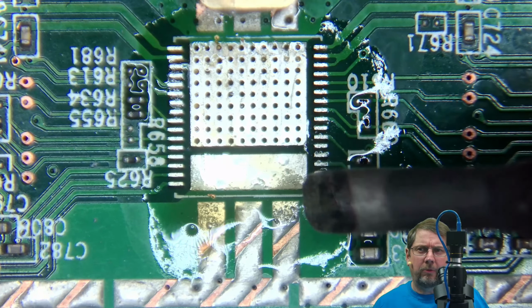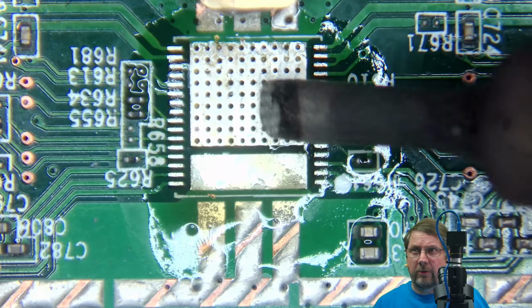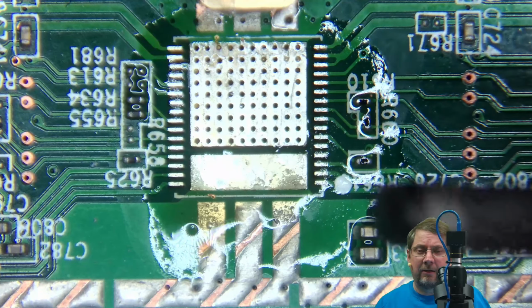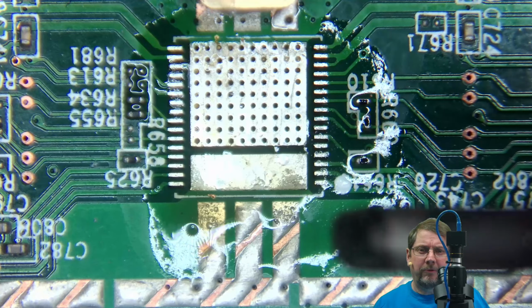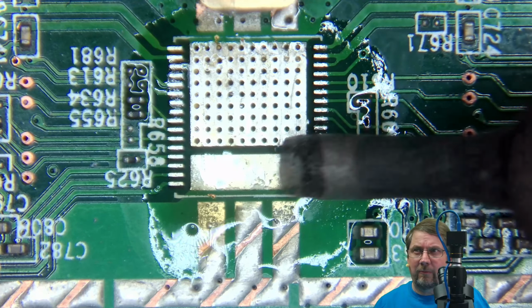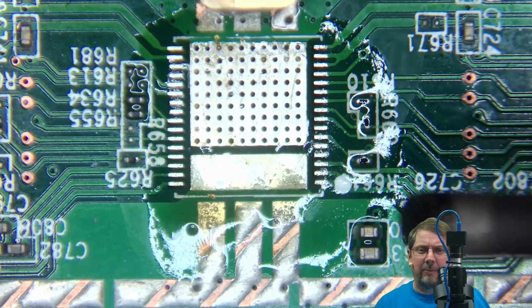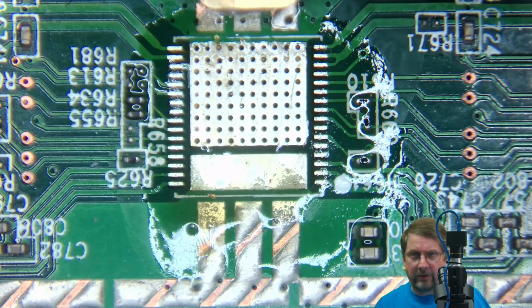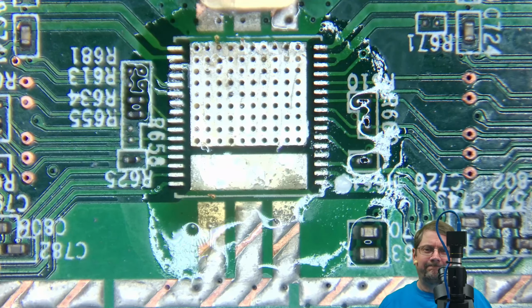You don't need to pull that hard. Now, when you're doing the larger pads here, you can put a little bit more pressure, but again, remember, if you're pushing up against this solder mask bridge right here, you can do damage to it. So, a light bit of pressure with your iron is really all you need when you're doing this. Let the heat do the work.